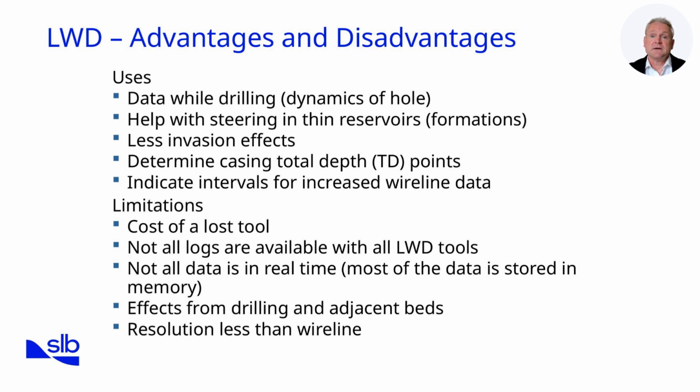On the other hand, there are limitations. One of the biggest concerns is the cost if an LWD tool is lost in hole. Not all logging services are available in LWD mode, meaning wireline may still be required to complete the dataset. In addition, not all data is transmitted in real time. High-resolution measurements are often stored in memory and retrieved only when the tool returns to surface. Finally, LWD logs can be influenced by drilling effects and adjacent beds, and their resolution is typically less than that achieved by wireline.